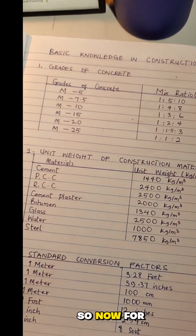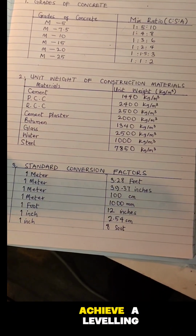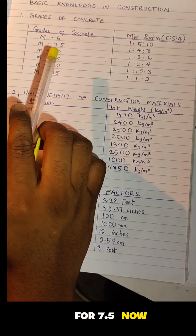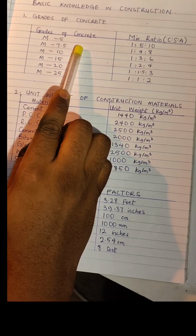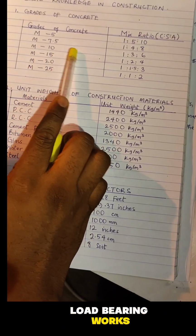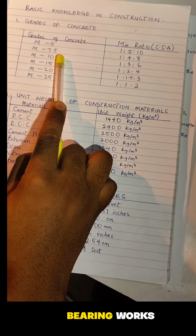Okay, so now M5 is mostly used when you want to achieve leveling, blinding, or non-structural works. For 7.5, it is mostly used for slightly strong blinding. You use this mix ratio. And then for M10, you use it for non-load bearing works. That is, if you want to achieve grade 10, it's mostly used for non-load bearing works.